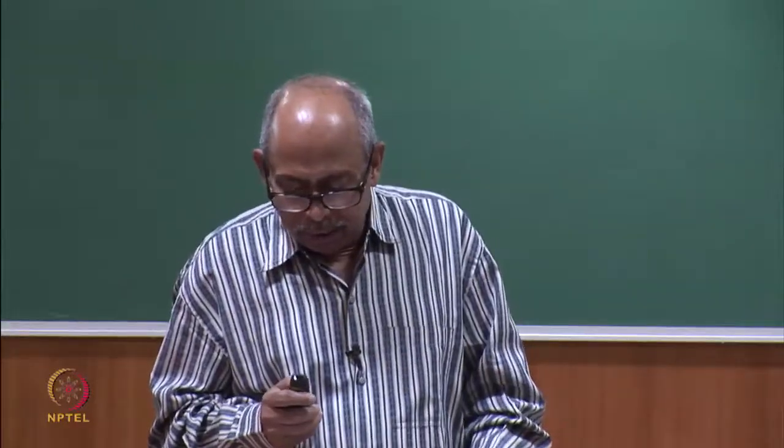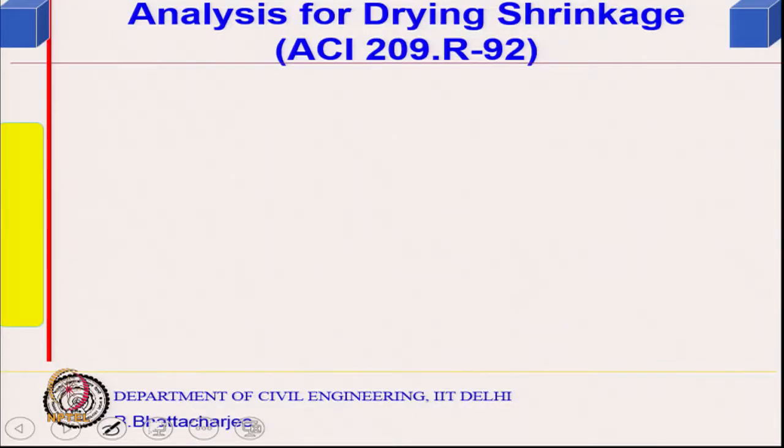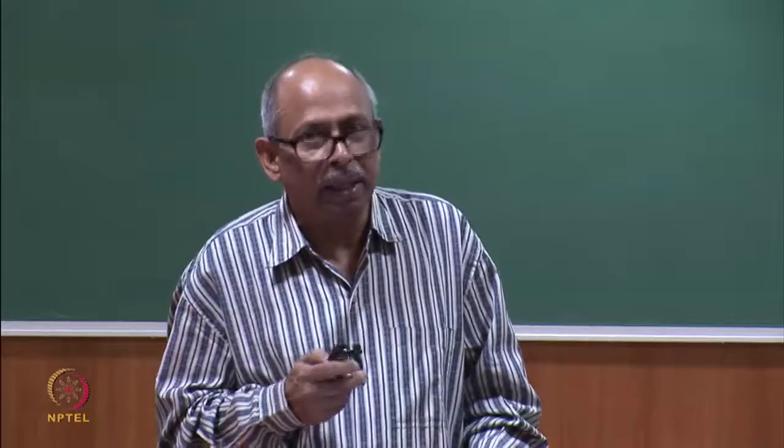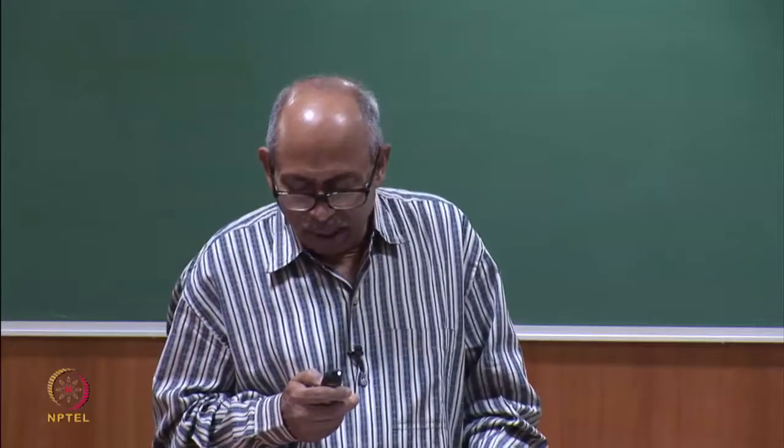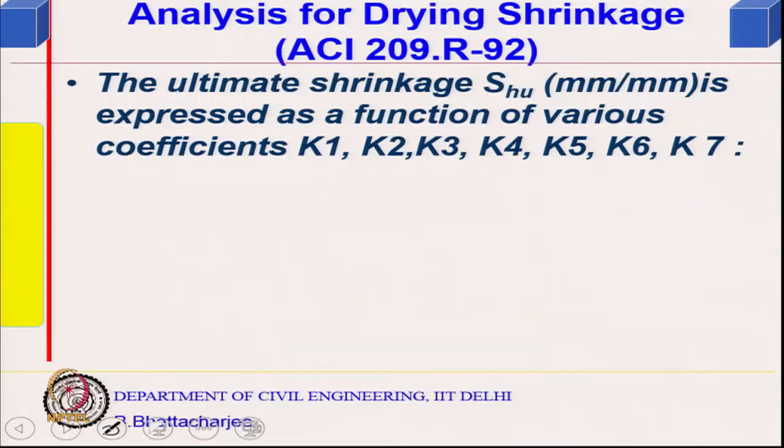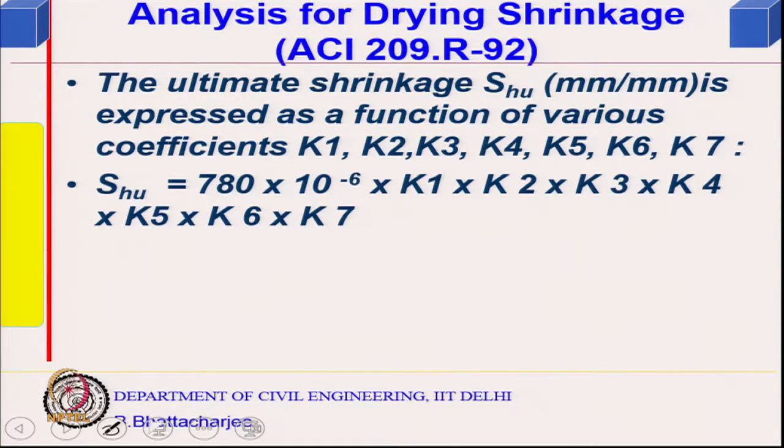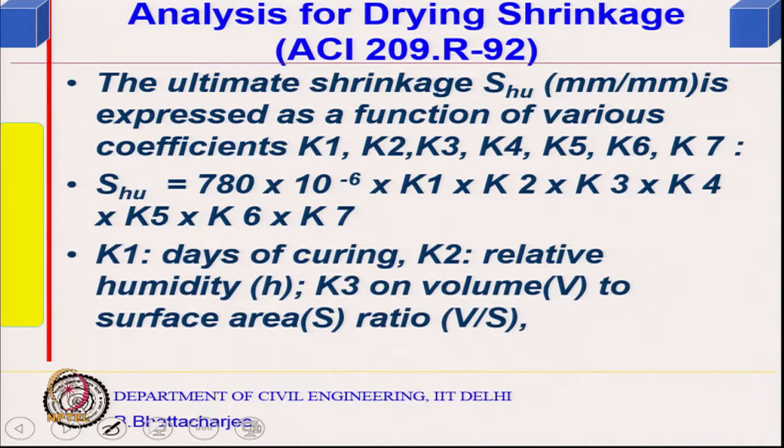In some cases you may have to predict shrinkage stresses, and ACI 209 gives you how to estimate shrinkage. Shrinkage cracks, in some cases we did use this. I will not go into details of estimation of shrinkage, but shrinkage can be estimated from ACI 209R.